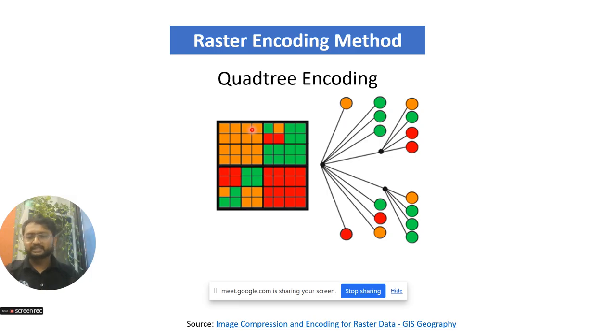Now, how do I check that the features are permanent in nature? Let's say if any temple, church, or any building is there which has not changed in the last few years, or any government building, PWD office, or any bridge, or any site, let's say a post office. If any permanent site or location is there, I will find that and I will consider the points of those locations as permanent points.